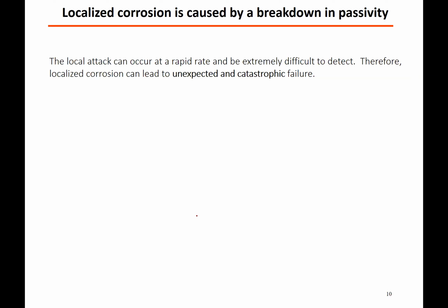You can do visual inspections while the part's in service. You can also take a part that you want to reuse again and do X-ray diffraction, X-ray microscopy. You can also do magnetic imaging, ultrasound, because if you design a material to a certain thickness, it will respond differently to an ultrasound if it's a thinner piece of material over time.